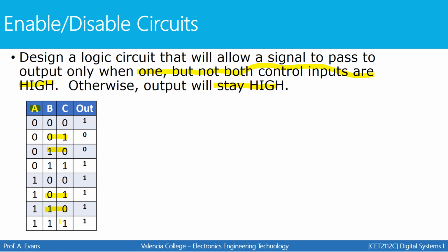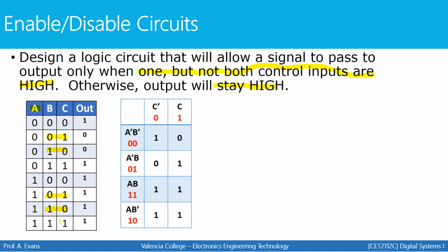Once we have our truth table, now we're going to write an output expression and simplify it using Boolean algebra or using a K-map. I'm going to do a K-map because it's much quicker and much faster. Here's what the K-map is going to look like. Remember, you're going to set this up with 8 cells. You're going to label the outsides just like we were discussing in the previous video. And you're going to fill in the outputs based on your truth table here.